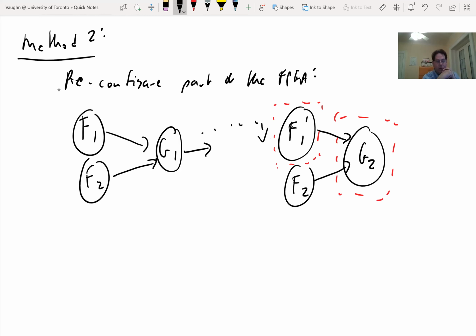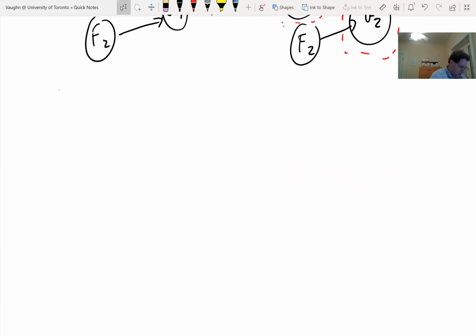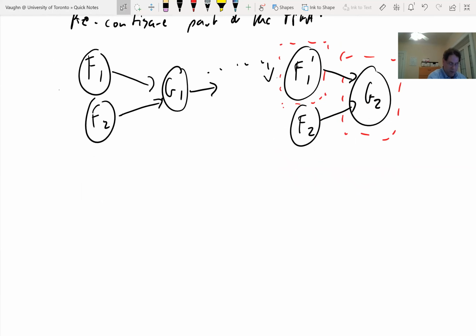And the FPGA hardware lets us do this, right? We can reprogram the whole chip. Partial reconfiguration is basically, almost all modern FPGAs support the ability to not just rewrite all of the configuration bits, those 100 million configuration bits, but to rewrite a subset of them. And nowadays you can rewrite, in most FPGAs, just one configuration bit at a time. So you could choose any subset of the configuration bits and rewrite them. So we can do this. At the hardware level, we could basically change the lookup tables. We could change the settings of those pass transistors or routing transistors, and we could make this happen.